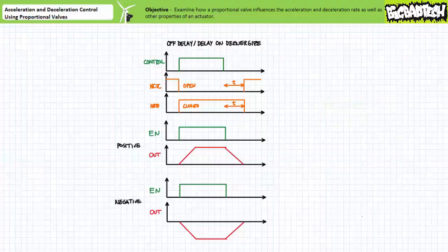The only real difference about the output of the off-delay timer in a ramp generator is that the ramp generator is producing a ramp transition from 0 to the respective positive or negative maximum and back again over a specific time period rather than an immediate off to on and on to off. Let's assume that the ramp up and ramp down period are symmetrical and that there is one adjustment point and the ramp up time equals the ramp down time. Additionally, let's assume the single adjustment point allows for values from 0 to 10 seconds.